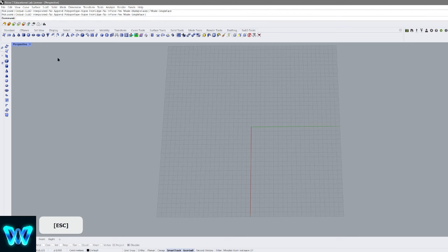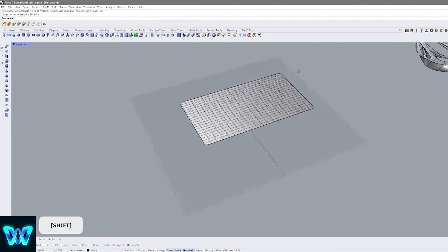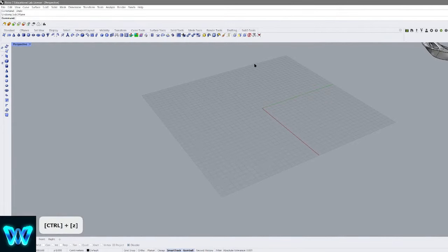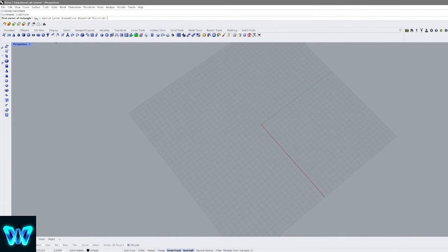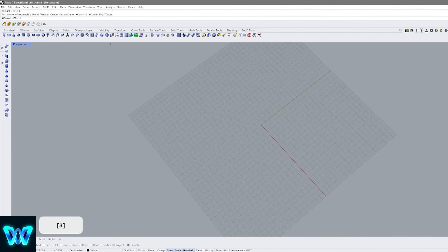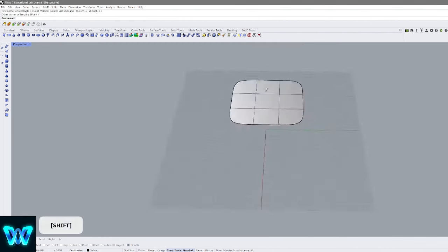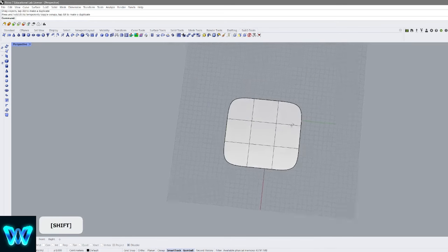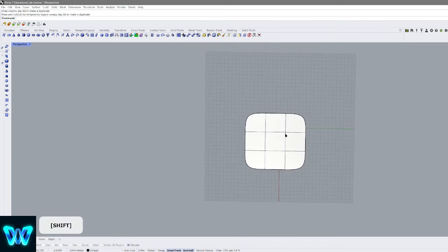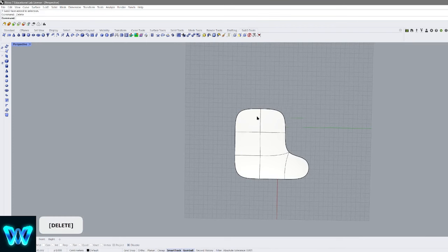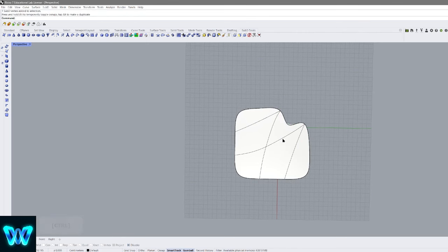All right. Then we've got the create SubD plane. This is the same thing, but now you have more faces in one SubD, so you can decide. You can make it 3 point, you can make it vertical, make it from the center around a curve, and then the count. If you make the count 3 by 3, now your plane will have only 3 by 3. This is a good way to start designing something, because now you have the freedom to delete some faces, and now you're able to start modeling what you're trying to do.